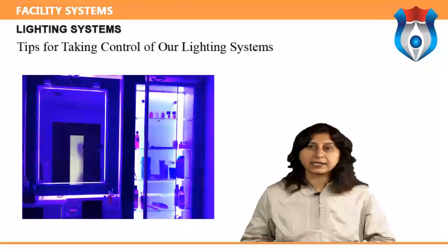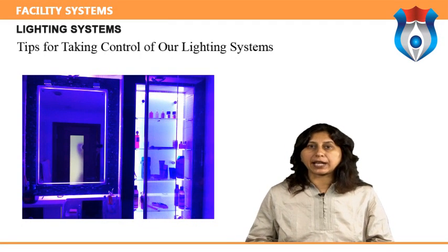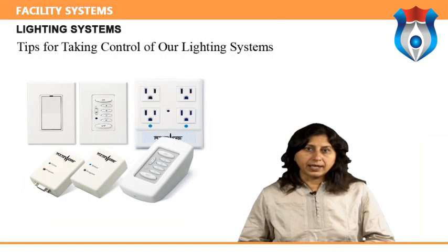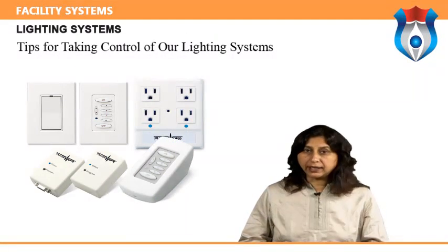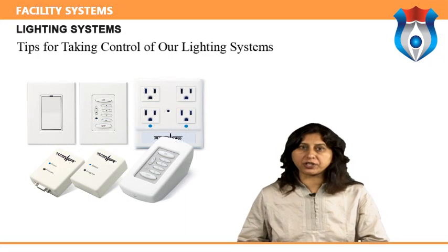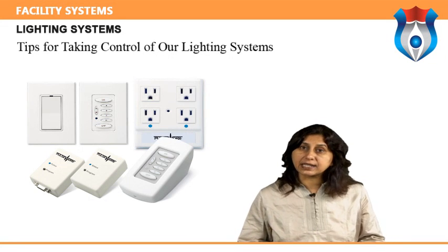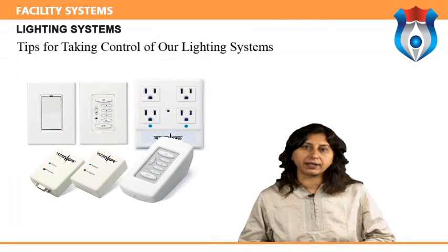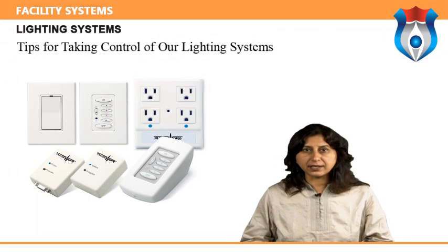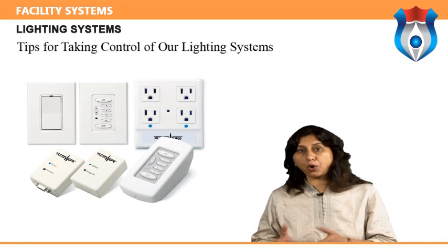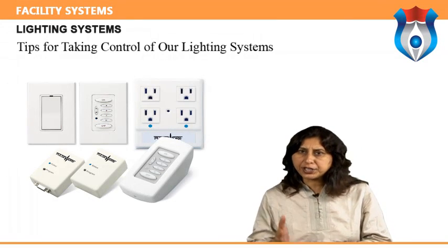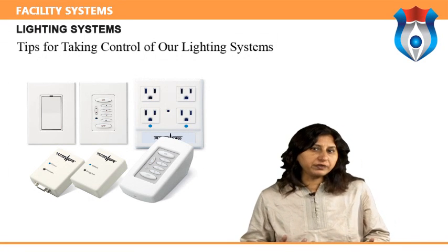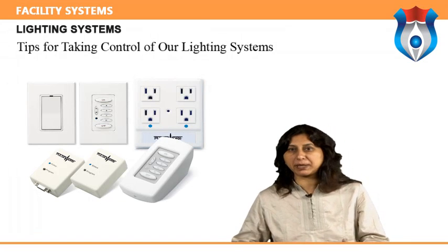Sensitivity controls determine the level of movement that will cause the sensor to activate the lighting system. Setting the sensitivity too high increases potential false on triggering, while setting the sensitivity too low increases the possibility for false off triggering. Using sensors to turn down or turn off lighting systems can reduce energy costs, and when applied correctly, they can improve working conditions and comfort for building occupants.